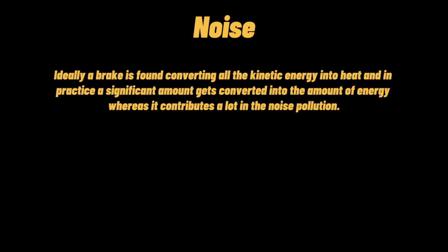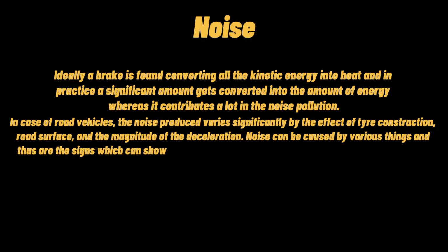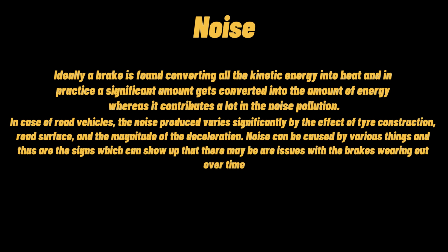Noise. Ideally, a brake converts all the kinetic energy into heat, but in practice a significant amount gets converted into other forms of energy, and it contributes a lot to noise pollution. In the case of road vehicles, the noise produced varies significantly by the effect of tire construction, road surface, and the magnitude of the deceleration. Noise can be caused by various things, and these can be signs that there may be issues with the brakes wearing out over time.